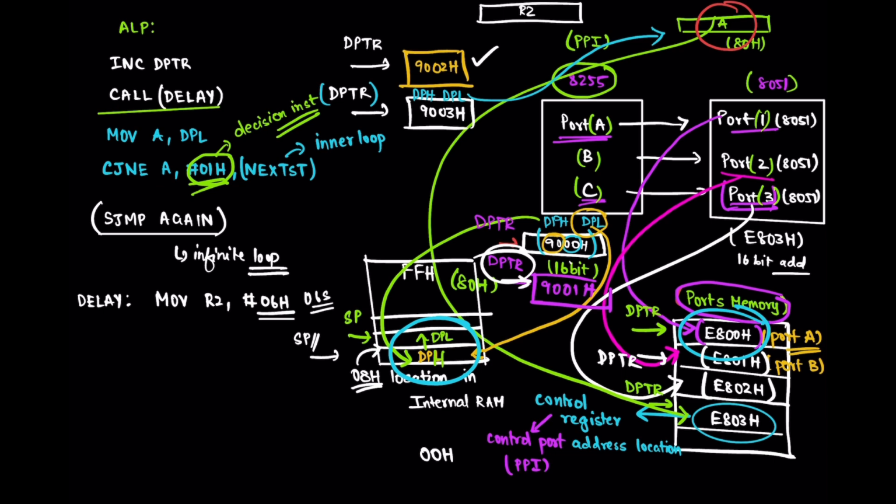Now outside the main outer loop, I want to create loops that repeat a block of instructions a specific number of times. So these loops can be used for managing the time or control sequences of traffic lights. So I'm going to give the name of the loop as loop 3, and then I'm going to write MOV R4, #0FFH. So I'm sending a value of 0FFH to the register R4. 0FFH corresponds to 255 in decimal. So I'm going to initialize R4 with 255.